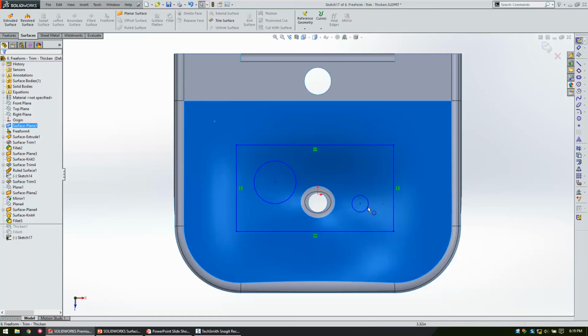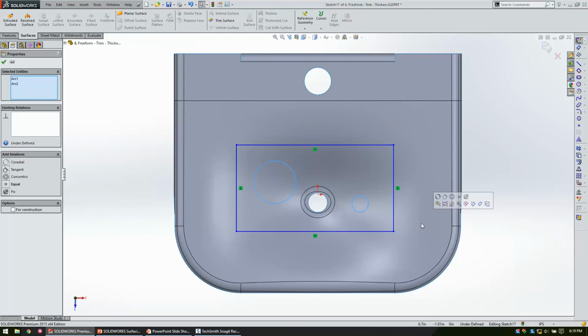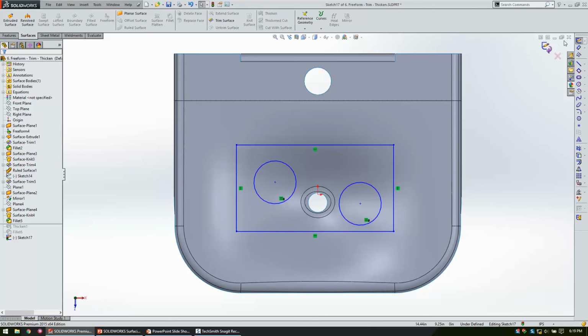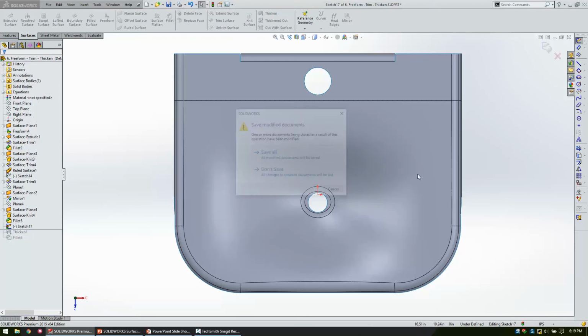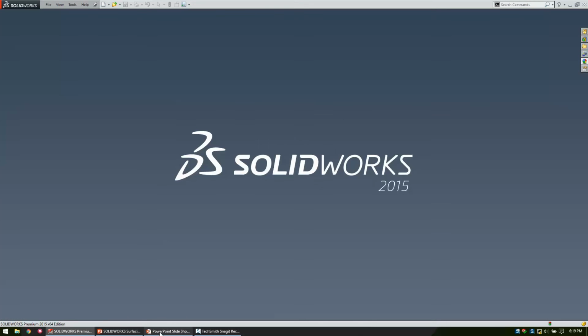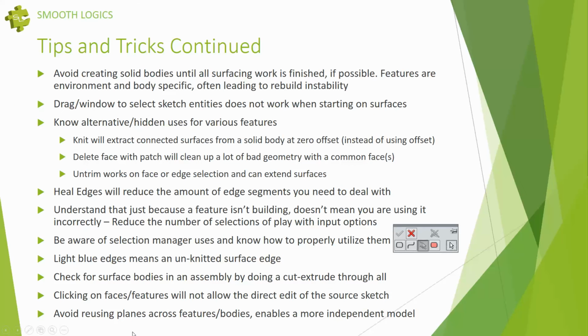So like if I want to make these two circles equal, I have to start out here and start out here and box select left to right, so I only select entities that are inside, not just intersecting the rectangle, and then I can make them equal. So just one of those things that can really frustrate you if you're not entirely certain what's going on because your box select doesn't work. Also, Control A would work the same thing. Whoops, wrong button. There we go.